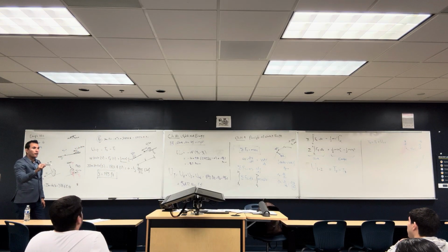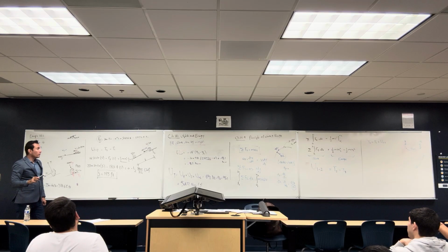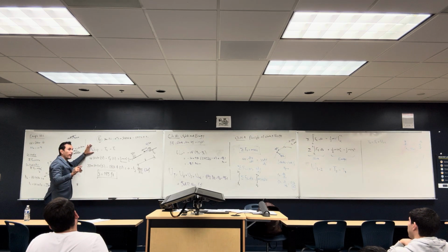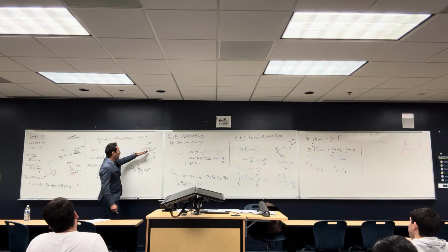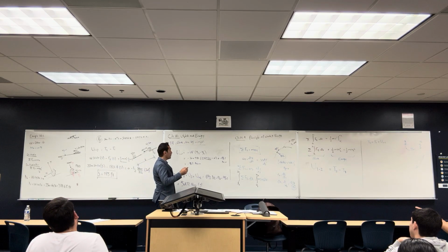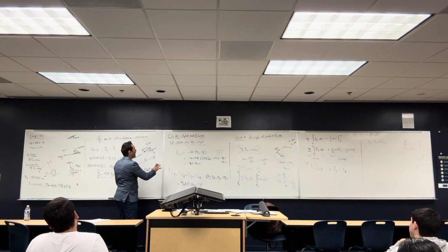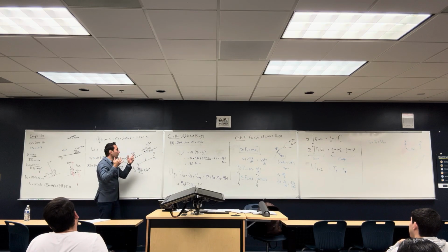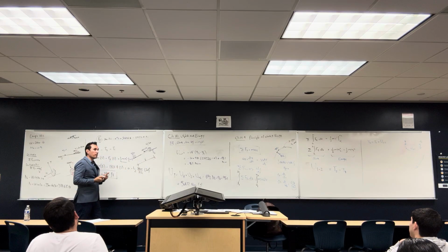I understand that U from 1 to 2 has to be the sum of forces acting on the object, right? U from 1 to 2 is the sum of the work. Yeah, but the forces that are doing work. The work of the weight isn't it negative? No, the weight is going down. Because of the formula it's negative at the beginning, but I told you, you can use the formula, but also you can use your intuition. This body's moving down, so the work is positive. But if the car is going up, the work is going to be negative.